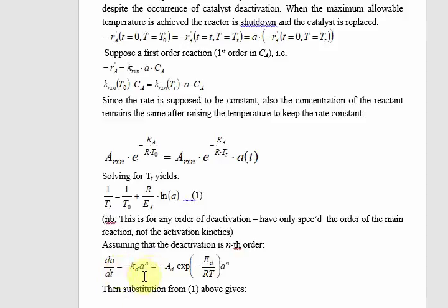This is, you could say, just a case study. So taking this example where these are the dynamics for the loss of activity, we can progress from here and look at how our temperature must change to keep the rate the same. Whatever our catalyst dynamics are, we would put them in here as the catalyst deactivation kinetics. And in this case, that's what we've chosen to pursue.